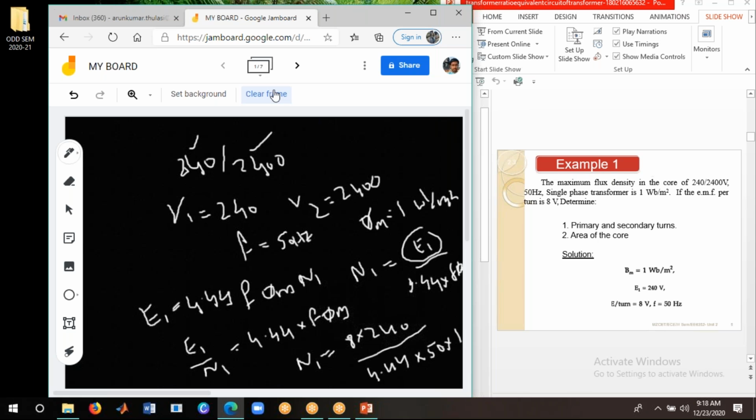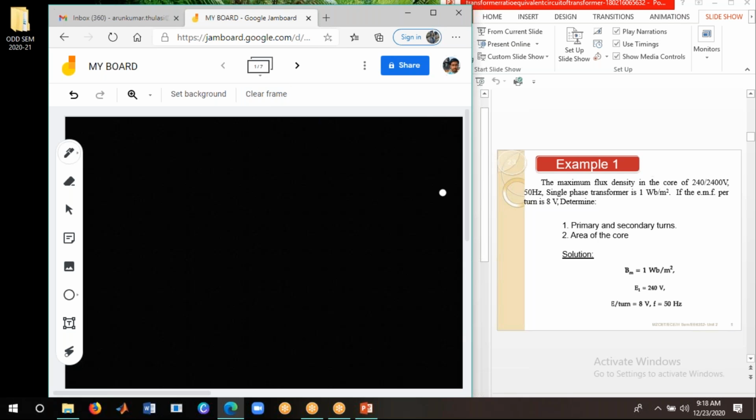See, we can find it in another way. So just find that. I will tell you one more method. Generally, from the transformation ratio, we can write K equals V2 divided by V1 and N2 divided by N1, right? So here, what they have given means, the voltage level is given by 2400 divided by 240. So that is 1 by 10.